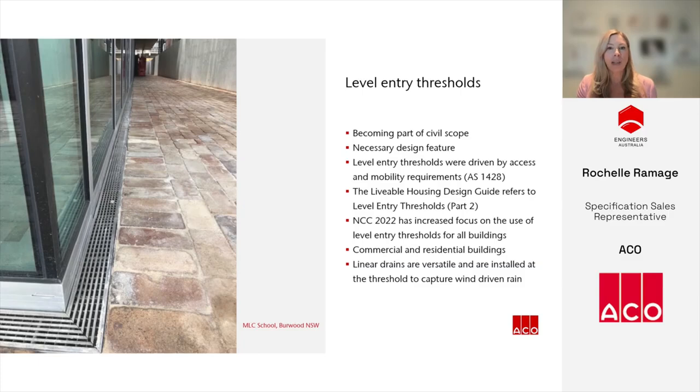Stormwater needs to be managed at building entrances, which is why civil engineers are now getting more involved in this area of design. To ensure barrier-free accessibility, level entry thresholds have become a necessary design feature at building entrances. These modern types of level thresholds were developed as an alternative to the conventional threshold set-downs. Originally, level thresholds were driven by the access and mobility requirements under AS 1428, and then reinforced through the Livable Housing Design Guide. With NCC 2022, there's now increased focus on level entry thresholds across both commercial and residential buildings.